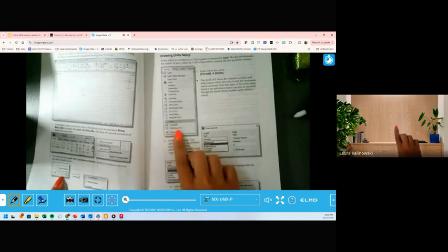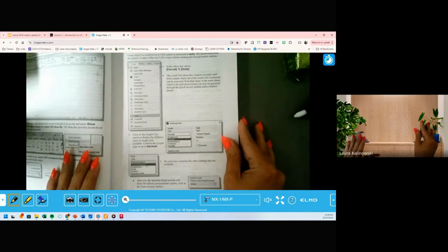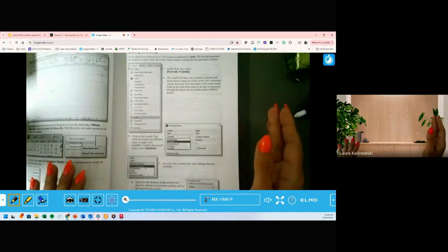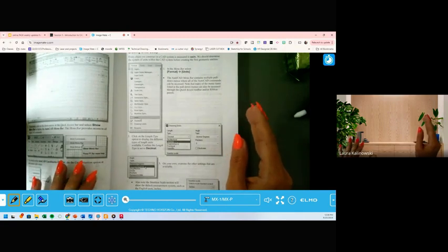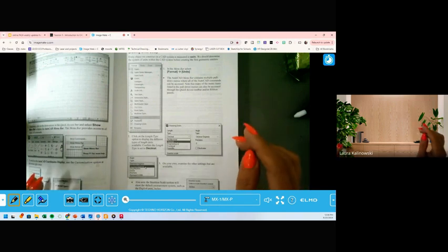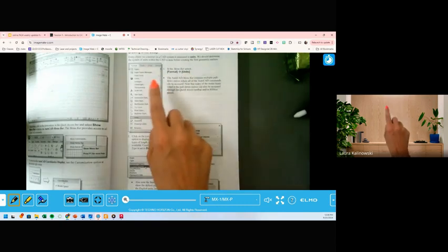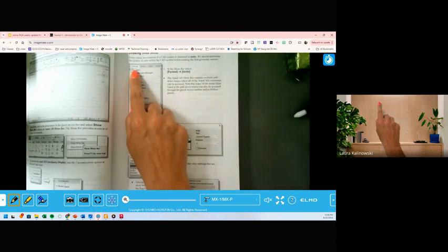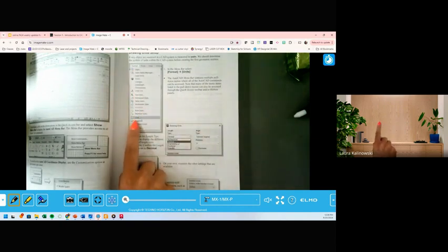So now that we have completed the menu bar, the customization, now what we want to do is make sure that we've set up our units correctly. So we've started in inches, because we started with AutoCAD.dwt, but we're also going to make sure that we are working in the proper style of units. So we will go up to that new bar that we just pulled up. We're going to go down to Format and go to where it says Units.